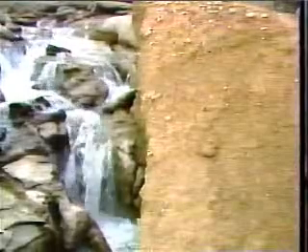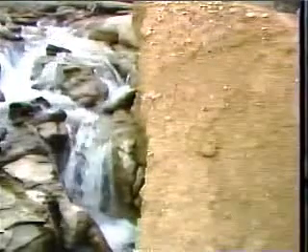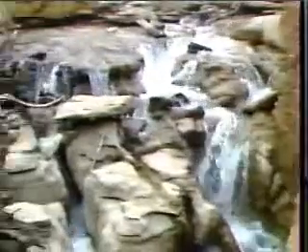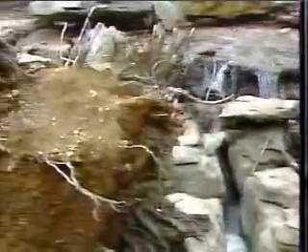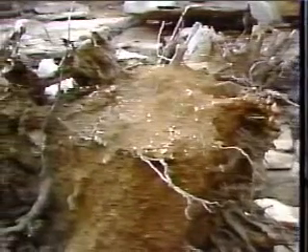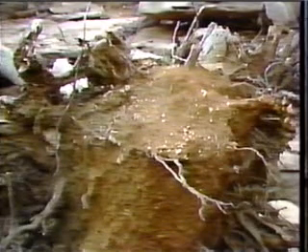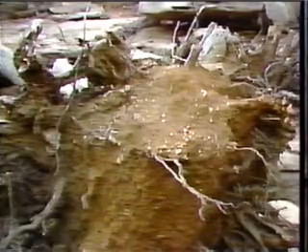Deep-rooted vegetation, such as large trees and shrubs, are particularly undesirable. Large trees could be blown over and uprooted during a storm. If this occurs near the dam crest, the resulting large hole left by the root system could breach the dam. Also, piping could begin when an uprooted tree shortens seepage paths.